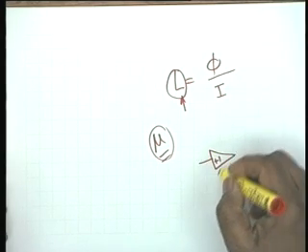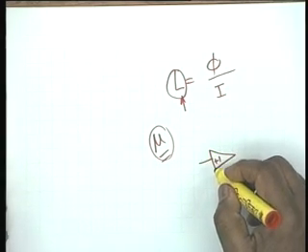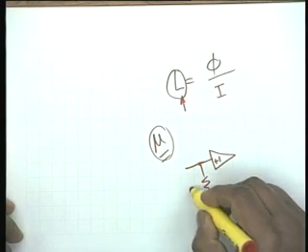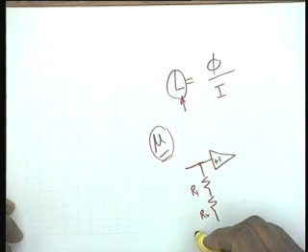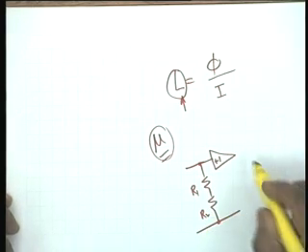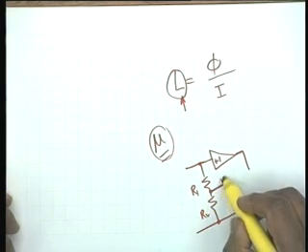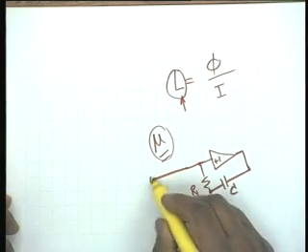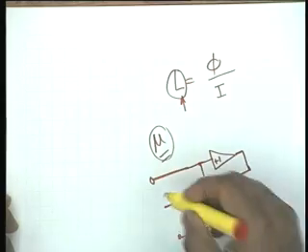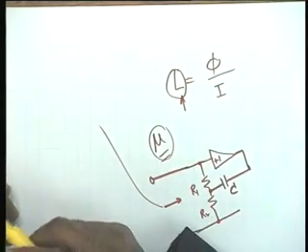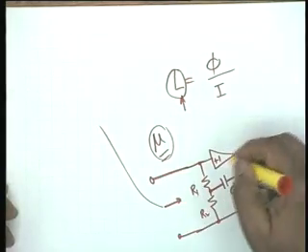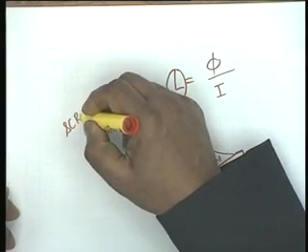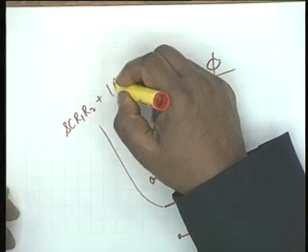If you have a unity gain amplifier obtained by op amps, and you have two resistances R1, R2 at its input, and a capacitor comes from the output, then you can show that this input impedance, we have done 110, so you know how to analyze such circuits, is SC R1 R2 plus R1 plus R2.